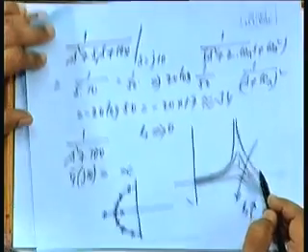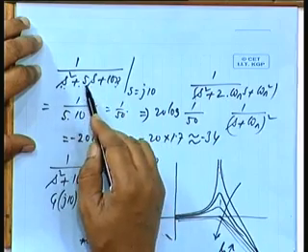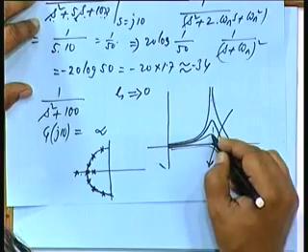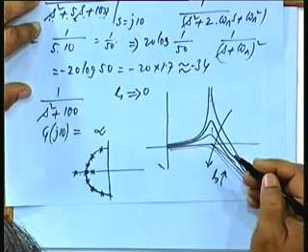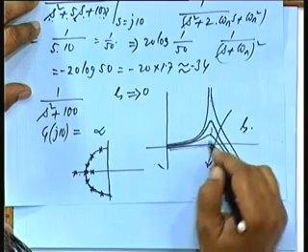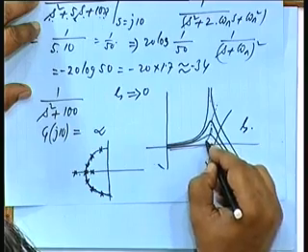Okay, friends, we will continue with some more examples on Bode plot. Last time we were discussing the plot for a function of this form, 1 by s squared plus 5s plus 100, that is s squared plus twice zeta omega n s plus omega n squared. For different values of zeta, you will find this peak value occurs at a shifted point here.